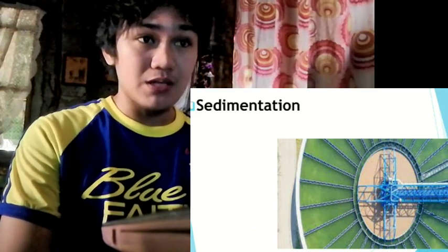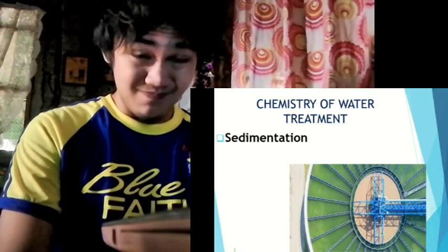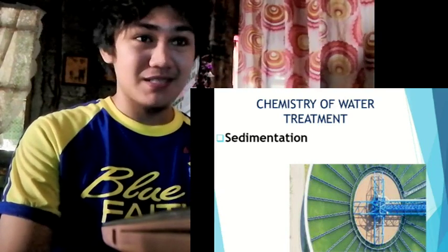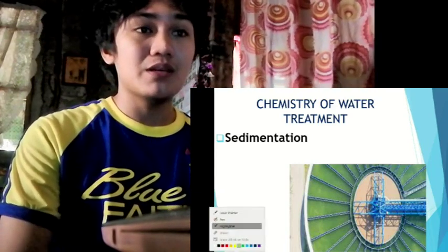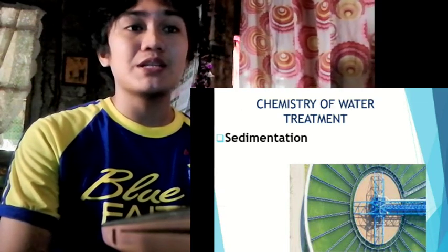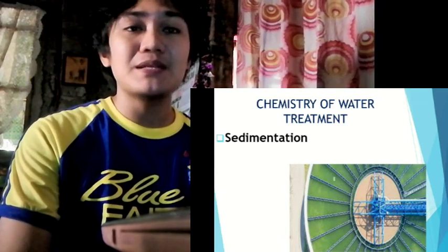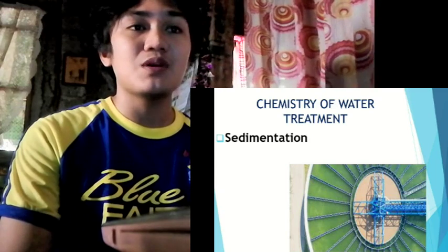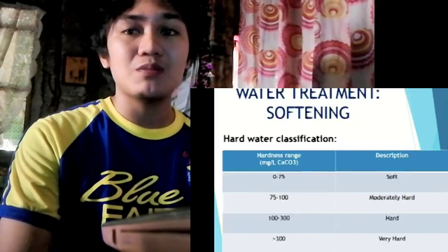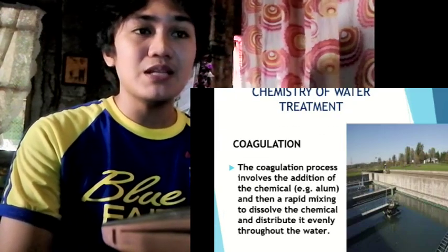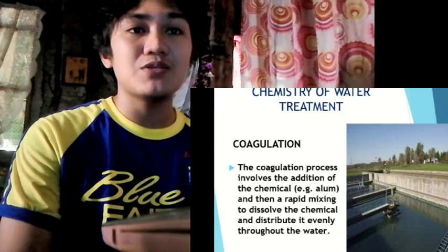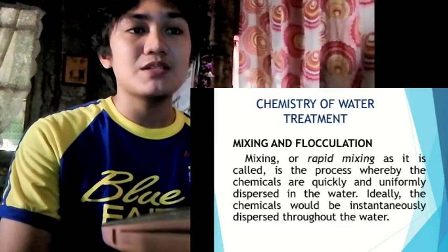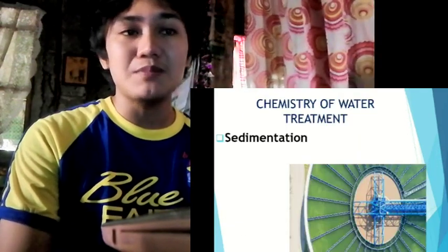Examples of these particles are sand and grit materials. Generally speaking, the only applications of type 1 settling are pre-sedimentation for sand removal prior to coagulation in a potable water plant, settling of sand particles during cleaning of rapid sand filters, and grit chambers.